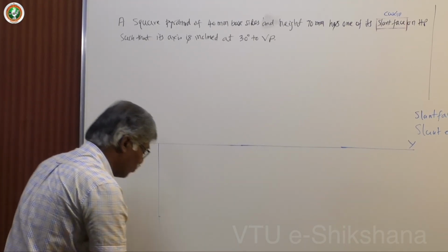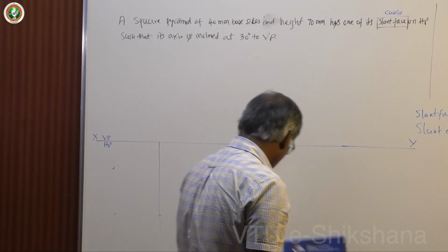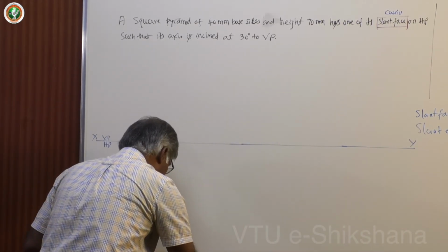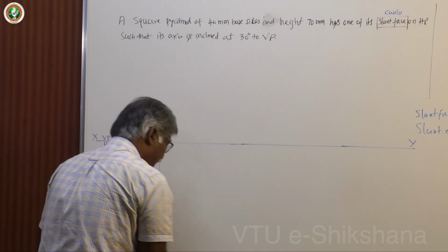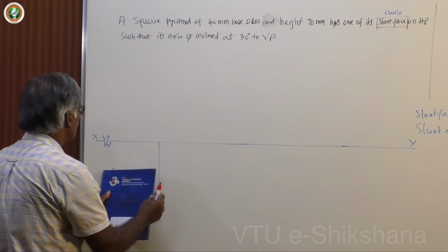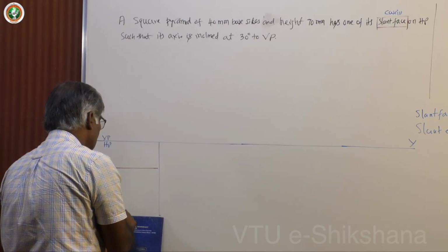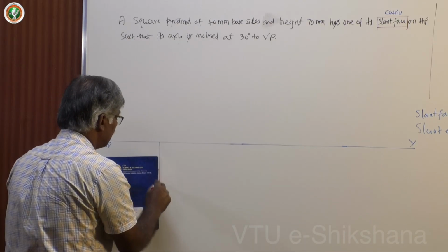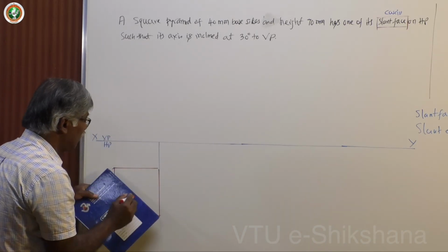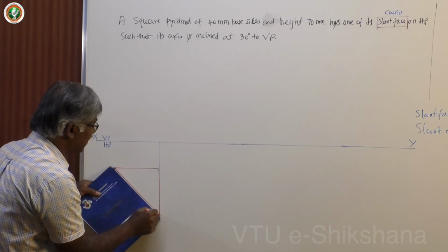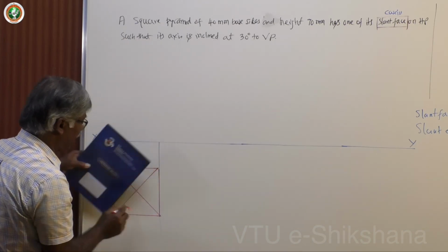You can choose the rectangle by 2 points in the computer and complete it. Here you can use any method to complete the figure. So, draw the top view with the given data, and also you must dark the diagonals that represent slant edges, dark lines only, unlike a prism.